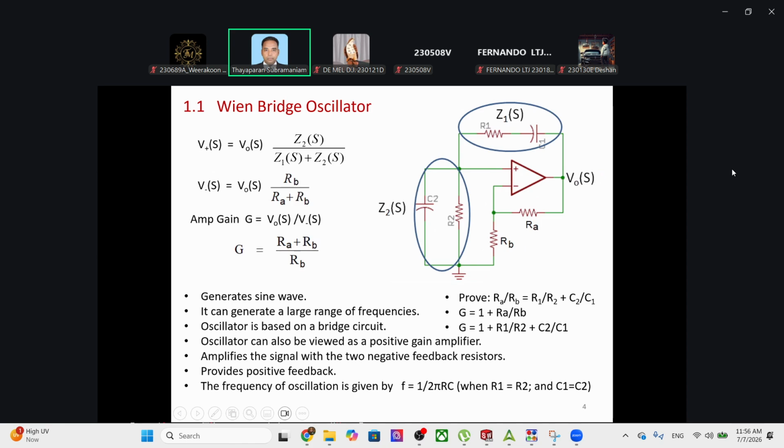It's like the Wheatstone bridge. Remember in A level, the Wheatstone bridge? In the Wheatstone bridge, you used it to measure an unknown resistance value, by making the current through the midpoint equal to 0. By making that, you have R1 R2 equal to R3 R4, whatever the relevant equation, and then all three resistances we know, we get the unknown resistance. Same fundamental here, you can measure the capacitance.